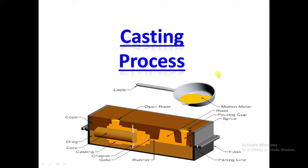Initially, if we want to make a part by casting, first of all the pattern is made. The pattern is nothing but the replica of the required part. Then it is kept inside the box and filled with sand. There is a process for how it is kept, that we will see later.